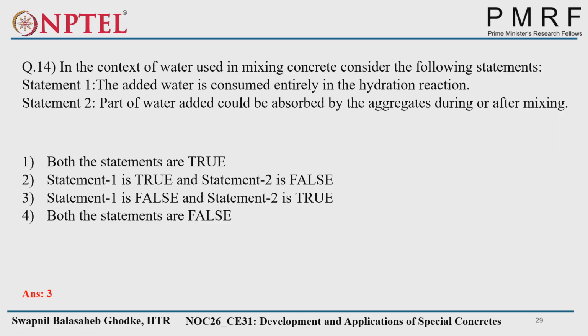So statement one is false and statement two is true, because the entire water will not be consumed by the hydration reaction. That's why, if you see some normal concrete scanning electron microscope images, you will see some unhydrated cement paste. And in concreting, some amount of water will also evaporate, because lab conditions are different. If you are casting in the field, there is always a chance that a certain amount of water will evaporate.